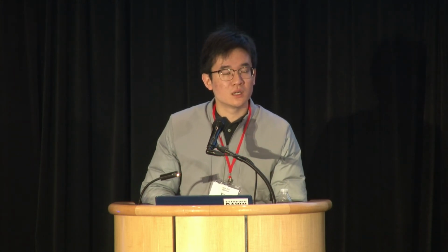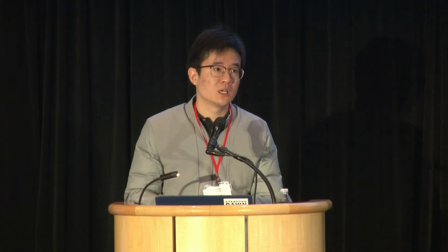Questions? Yusuf Clarkerman of Bloomberg. I was wondering if you tried with the V100 to do custom CUDA kernels which did loop-based parallelization, if you think you would get better results? We actually used the cuDNN implementation for both the LSTM cells and the GRU cells. But I think if you look at the cuDNN kernels for those two, you will find that the first part of the RNN kernels are still implemented using a streaming GEMM instead of using loop construct. Whereas in contrast, our implementation can fuse the loops in the first part and the second part.